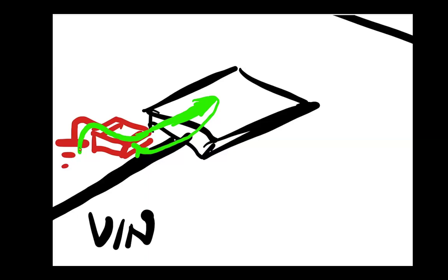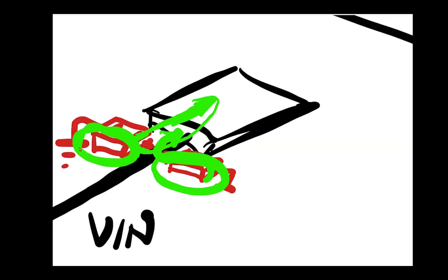Francesc was explaining that the technique to reduce the emissions from this capacitor is to put a capacitor that is symmetrical, no? Because then the current goes in opposite direction, and then you have 2 loops with currents in different directions. So the magnetic field at this point is minimized, because one of the loops cancels the magnetic field created by the other. So I suppose that with near field probes you are identifying that around your decoupling capacitors, or capacitors that are in parallel, you have these high frequency currents.